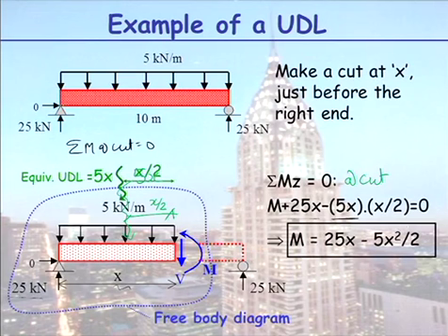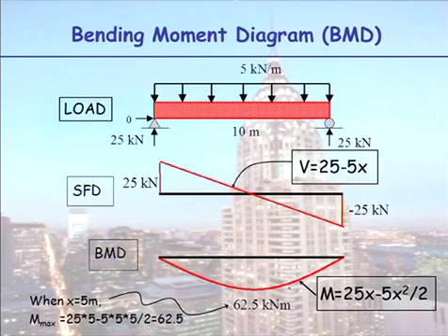We know my moment is 0 at a pin support, don't we? 10 metres along, substituting 10 in there, 10 squared is 100 times 5, 500 divided by 2 is 250. Take that away from 250, your moment is 0. So what we've come up with here is our bending moment diagram. There's the mathematical expression we got for it. Yes?